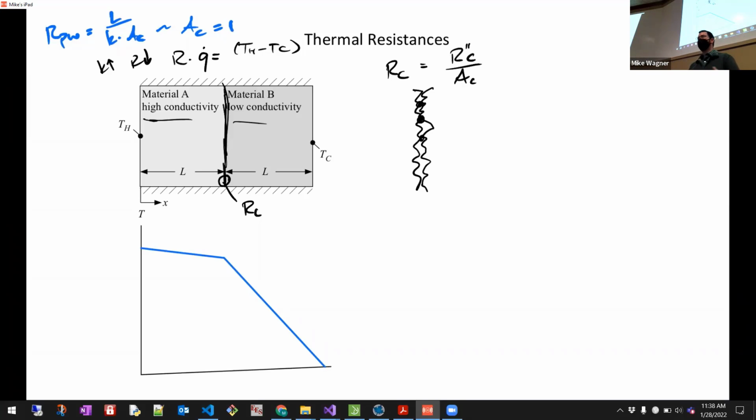All the normal mechanisms of conduction heat transfer are suspended at this point, except for those little areas. In the space between, maybe you have radiation across, maybe you have conduction through whatever is there. If it's air or oil or whatever is in that gap, you'd have conduction there. Maybe some convection, although usually the length scales are small enough that it can't occur. But basically there's a penalty for not perfect alignment.